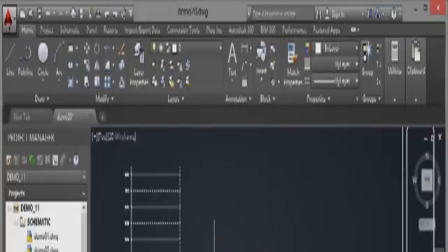Now, the nice thing about this is because I'm using the stretch command now, I can utilize my object snaps and my polar tracking. So if I use that endpoint snap there, I can obviously snap to it. I need to make sure that my snaps are on, so I come down to the status bar and just click there, make sure that endpoint is on, which it is now. Come into the drawing area like so, and then when I hover there, I get an endpoint snap. So I can do this accurately.